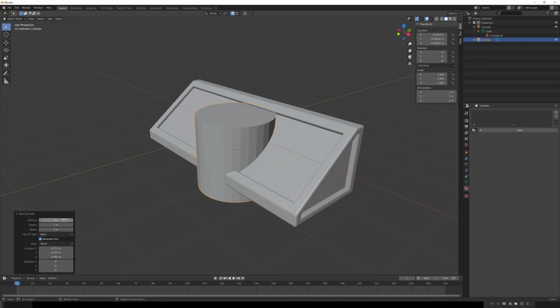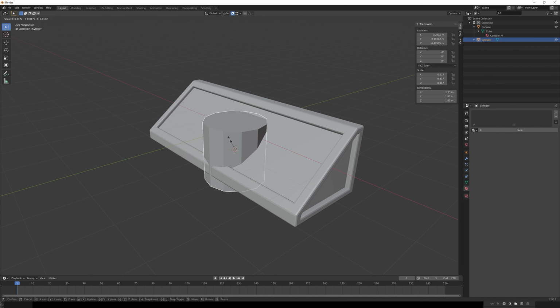Now we have the chance to reduce the number of sides on this object because this is quite a lot. On vertices, if I click this down, you'll notice that creating something around maybe 12 or maybe 16 is going to be a good number to start with. Let's go ahead and pick 12 for now. Next up, of course, we can use the scale tool, and then we can, of course, hit the Z key for vertical, and we can make this scale down a bit.